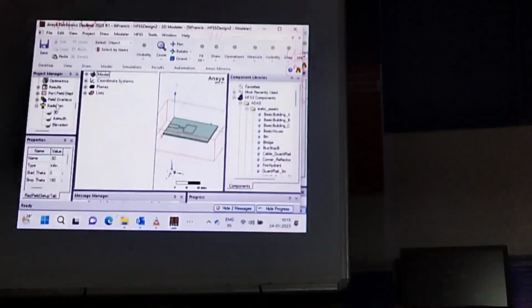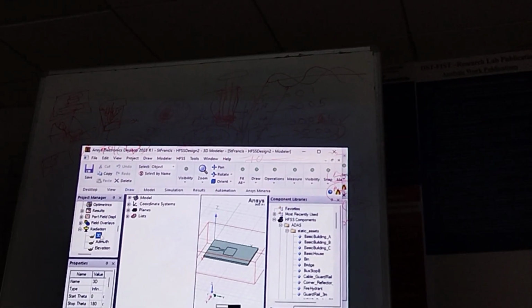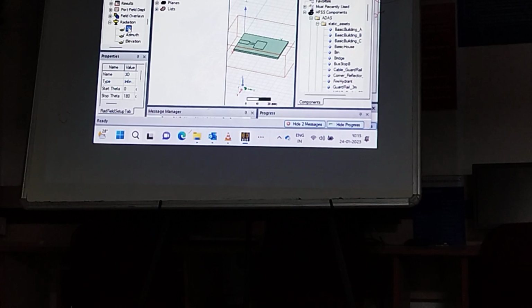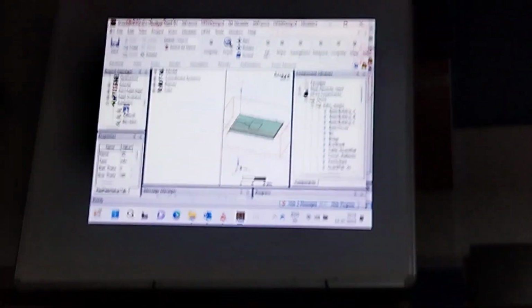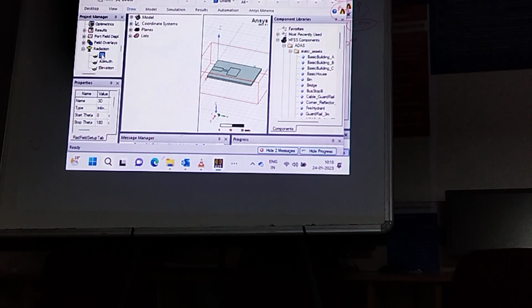So actually, once you radiate it, suppose we had radiated any kind of antenna placement yesterday. Actually, I did not run that particular simulation yesterday, so the radiation pattern has not been generated. So once you run that, for example, this 3D pattern, if I want to export it to EMIT directly, how the far field scenario is overall, that far field data, if I need to export here and incorporate in EMIT, then